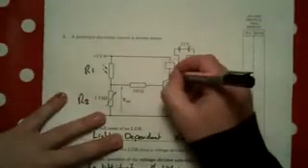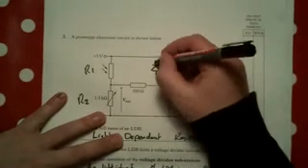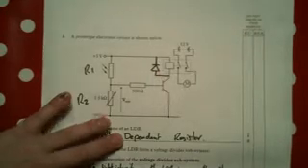Second part of the question now. Complete the circuit diagram to show how the diode could be used to protect the transistor. Well, the EMF, which can damage semiconductor components, needs to be escaped at power down. So we put the diode in just there. State the name given to this condition when VBE is 0.7. Saturation.